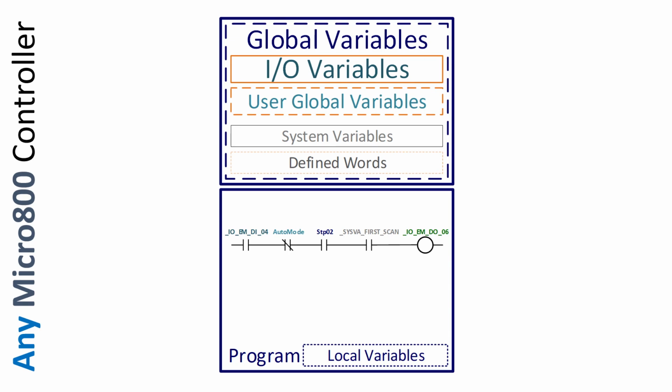So the first 4 instructions are never on or off. They are true or false. Consider the first 2 again. True if on, true if off. The first instruction is true if the bit memory is on. The second one is true if the bit memory is off. That's why when you look at these instructions, you always want to keep in your mind they are never on or off. They are true or false. Now the bits in memory might be on or off, and that determines whether they're true or false, but they're true or false, never on or off.